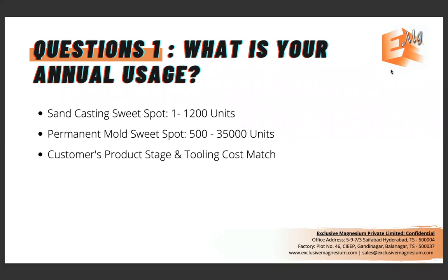So we recommended that a good alternative would be an aluminum pattern in sand casting, because even if that 1,000 units didn't come in later, we would still be able to do 50 more, 100 more, 200 more in a viable way, and that pattern could still be used for larger volume. Whereas a wooden pattern would have lost its value in 25 units at max.